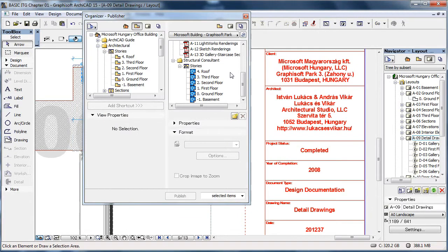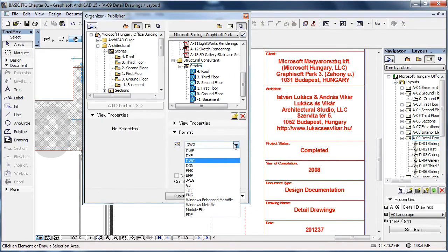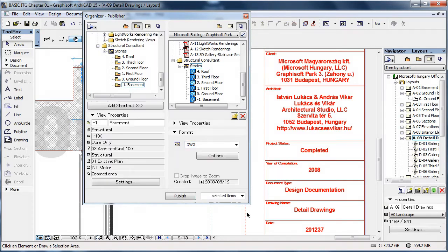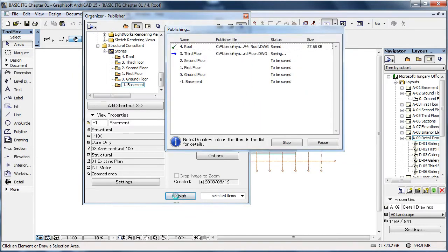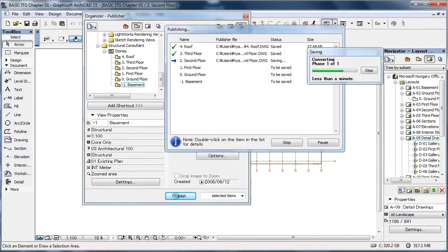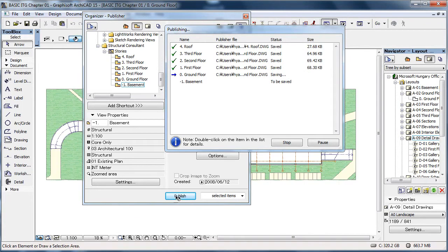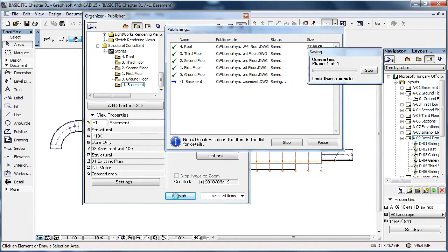And since there's more to life than printed documents, your CAD program must also interface with other programs from other disciplines. ArchiCAD supports interoperability with formats such as DWG, DXF, and PDF for daily data exchange. All documents are published through the automated publisher. Once defined, a publisher set retains all the publishing properties, so you can output a new set of data at any time without needing to input these properties again.